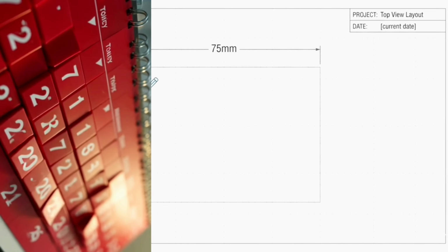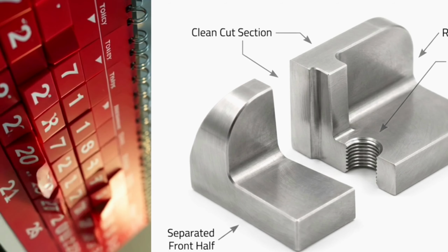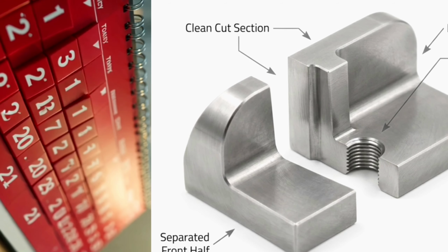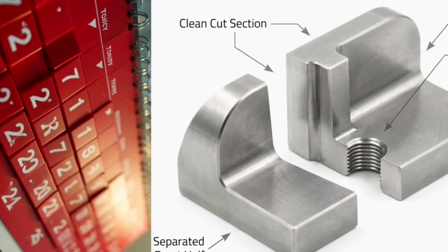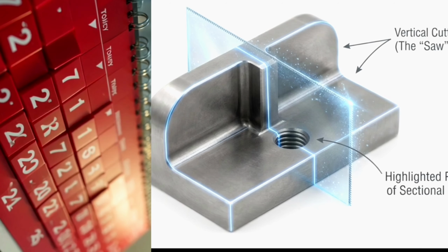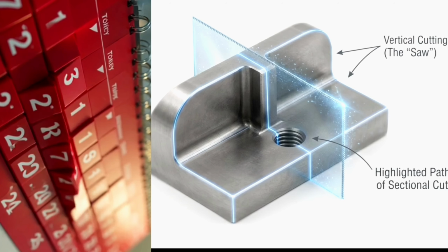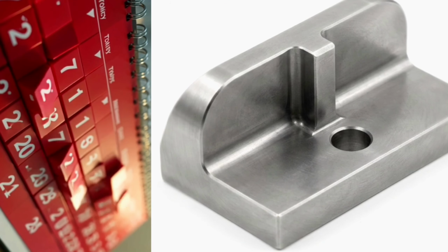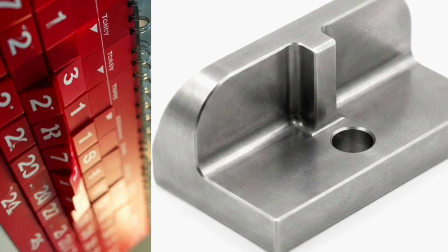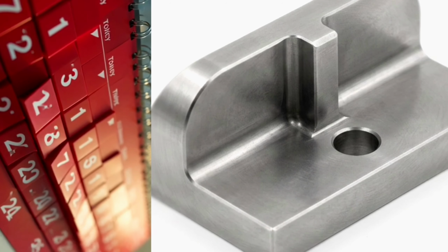By following these steps, analyze, project, and section, you can master any engineering graphic. This technique is essential for anyone in mechanical design or CNC programming. Project lines. This allows us to dimension the 12 mm internal hole and the central rib directly, ensuring the part is manufactured exactly to spec.